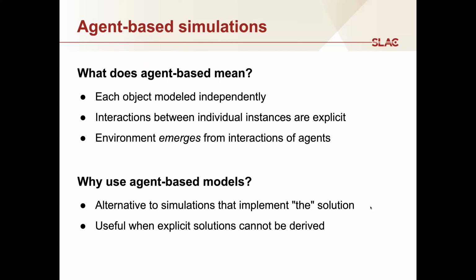Gridlab-d is what we call an agent-based simulator. And so what do we mean by agent-based? If you think about how traditional simulations work, typically you implement a solver for a set of differential equations, either ordinary differential equations, or if it's a dynamic transient solver in power systems, it might be differential algebraic equations.